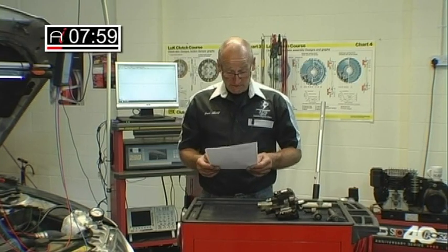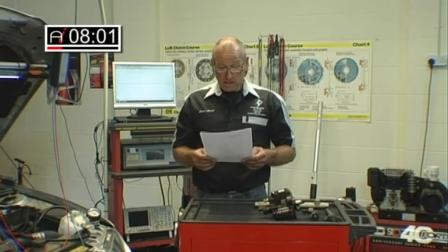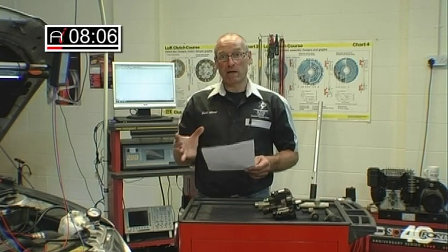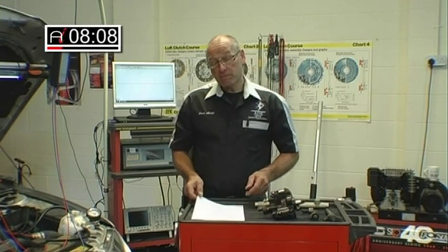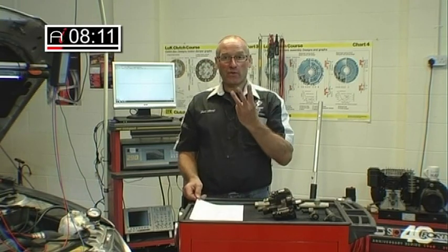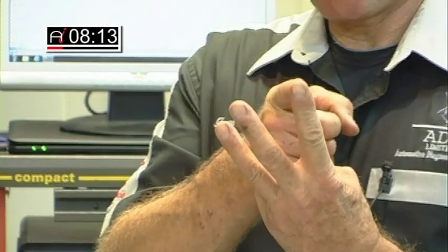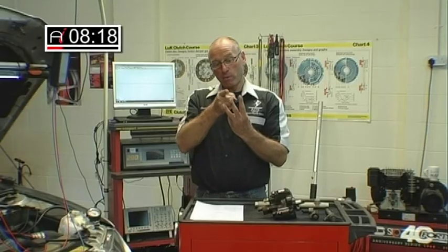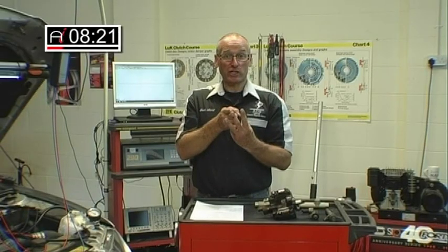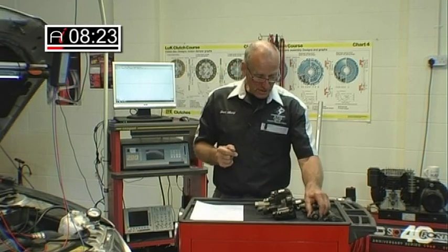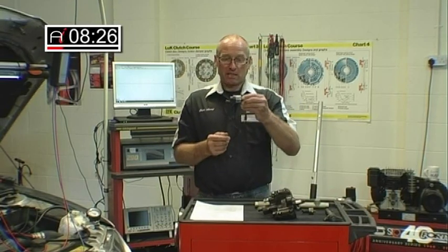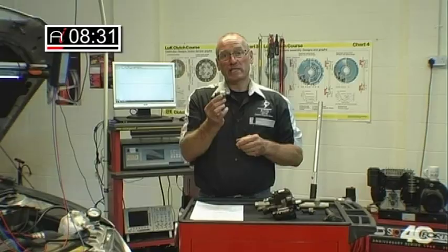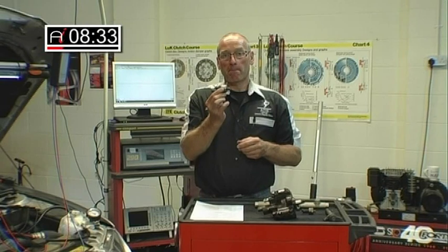The next fault, P1190, intermittent, rail pressure plausibility, control deviation too large. Another huge mouthful. The number of potential causes in that are enormous. Three phases of common rail: storage and priming, pressure generation, fuel delivery. We potentially have a problem with pressure generation, deviation rail pressure. What that means is that the DRV, Druck Regulation Ventil, it's a pressure control device. It controls the escape of fuel back to the tank.